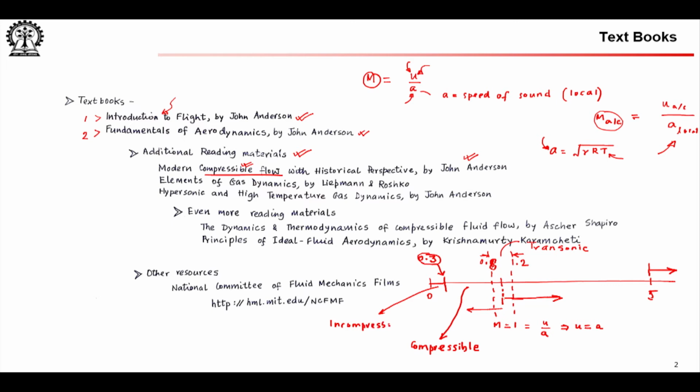So, below Mach number 0.3, flow is subsonic, of course, because Mach number 0.3 is less than 1, but on top of that, flow is also incompressible. Incompressible means that your density in that flow field is neither changing with time nor changing with space. So, density is constant for this flow field, incompressible.